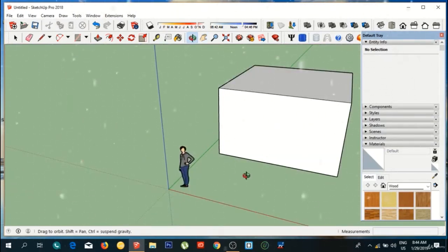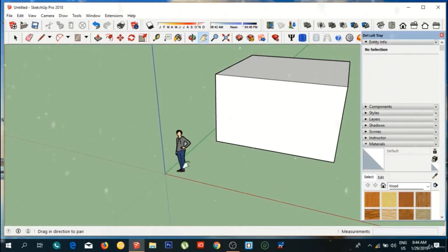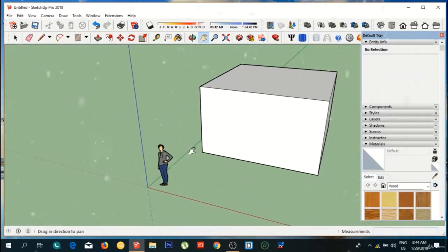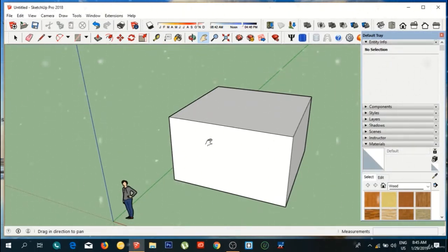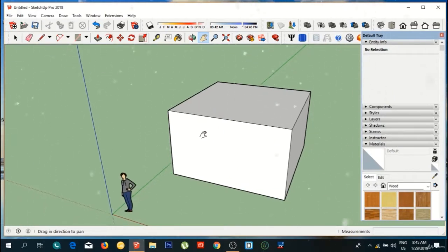This axis represents the directions, and the green line or the green axis going to the north, and the dashed line of green going to the south, the red line going to the east, and the dashed line of red going to the west. So when we are facing the PV system, we will face it to the south or the north according to your location in the world. As we discussed in the azimuth angle, we will face the PV arrays to the south if we are in the northern part of the land, and we will face it to the north if we are in the southern part of the land.